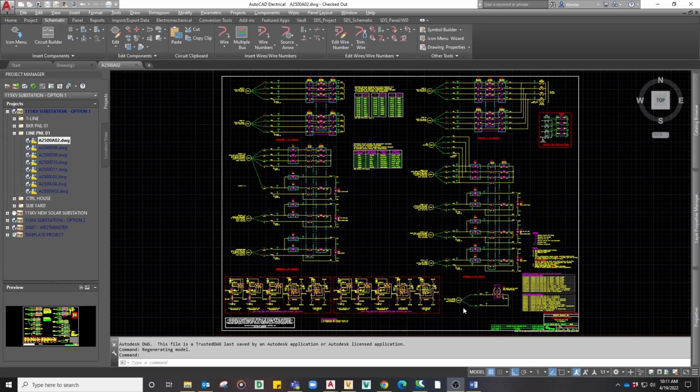This cable always references the AC distribution panel connection diagram, not another schematic diagram. AutoCAD Electrical requires both ends of this cable to be connected to schematic symbols, not just for proper annotation and referencing, but also because AutoCAD Electrical draws on schematic information to produce cable from to, wire from to, and other reporting. Since this is a conversion example where I chose to maintain the current look of the customer's current AutoCAD standards, I've chosen to create supplemental design standard schematics to fill in the missing gaps in the schematic material.